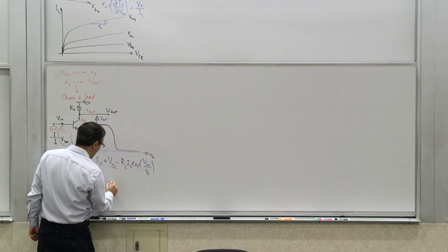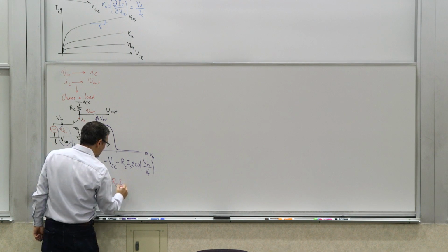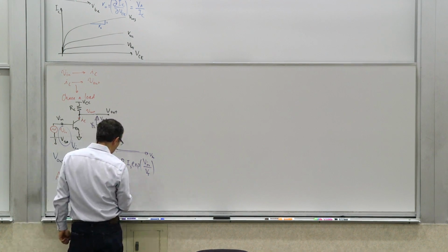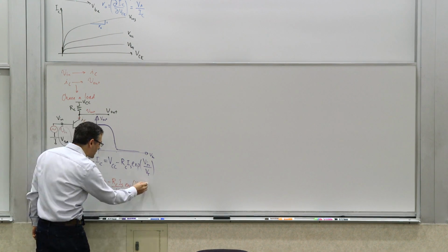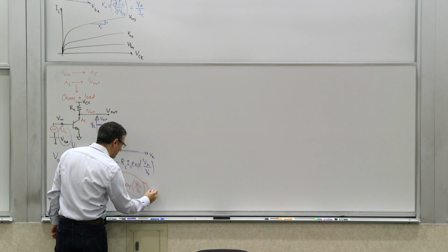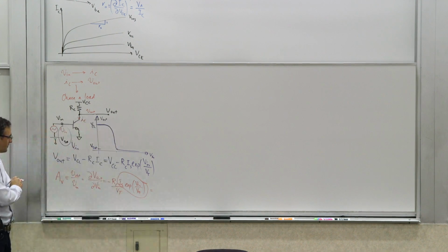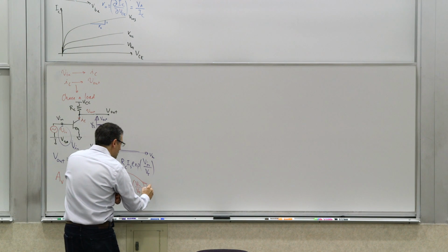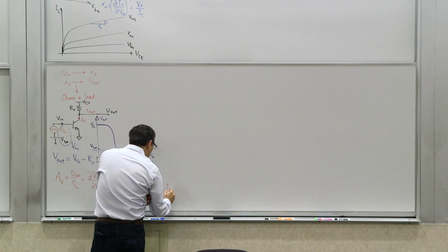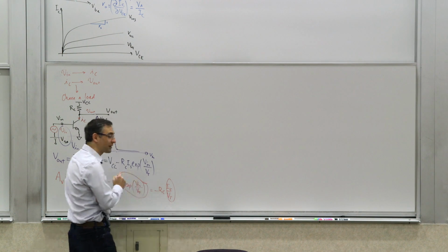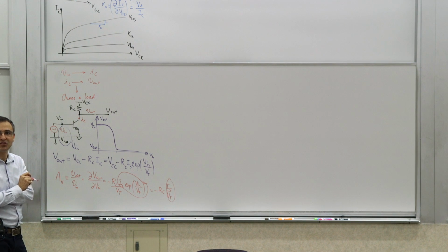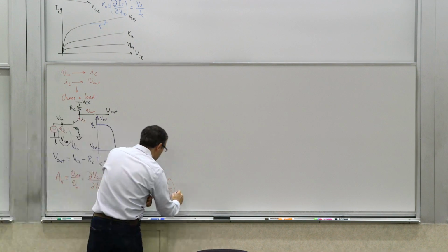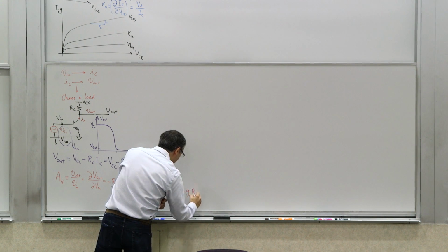So what is the derivative of this thing? It's negative RC IS. The derivative of the exponential gives you a 1 over Vt times the exponential of V in over Vt. Right? What is this quantity? Do you recognize it? This is the IC itself, right? So I can write it as negative RC IC over Vt. And this quantity should be recognizable too. Now, look up there in red. That's GM. So it's negative GMRC according to this calculation.